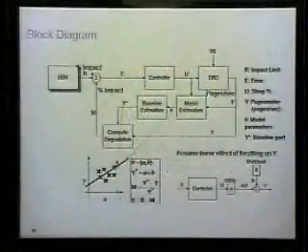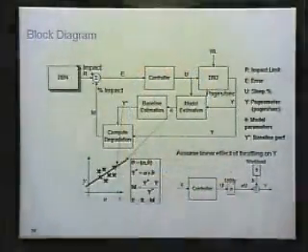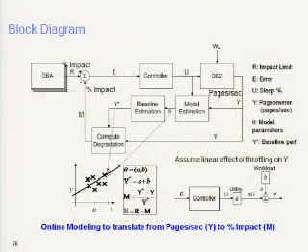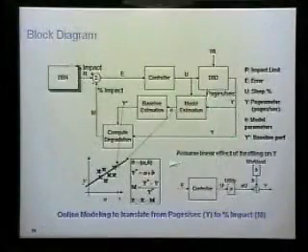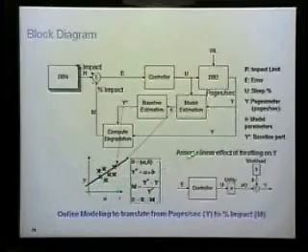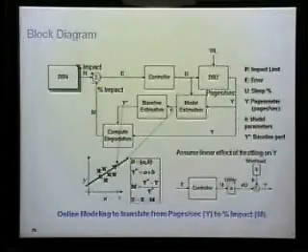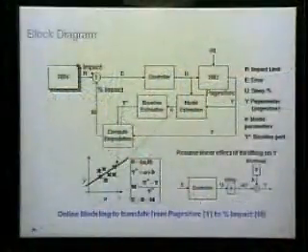Okay. That shows you the part about computing the linear effects, with the various computations that we did there. This also goes back to the model estimation over here. These points that you see here and these estimates are all done online. You couldn't do this offline and get anything that was going to work for a production system. So we used a technique called recursive least squares to look back at the last n values and then compute what this slope was.